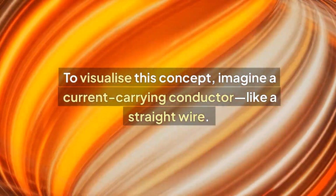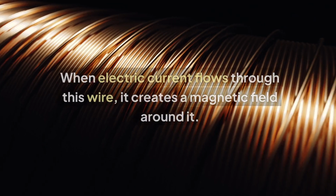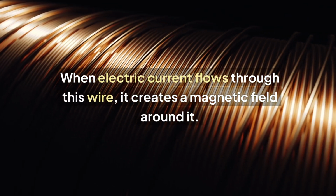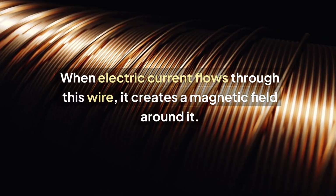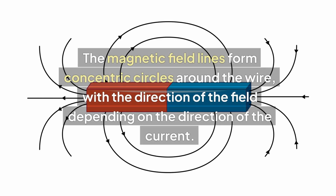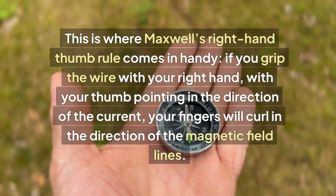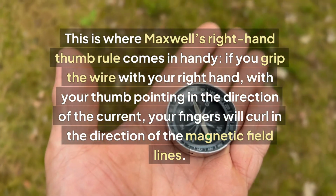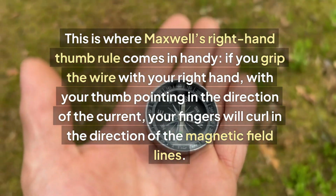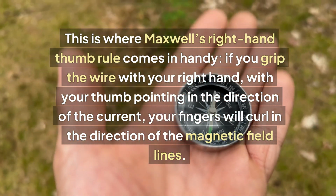To visualize this concept, imagine a current-carrying conductor, like a straight wire. When electric current flows through this wire, it creates a magnetic field around it. The magnetic field lines form concentric circles around the wire, with the direction of the field depending on the direction of the current. This is where Maxwell's right-hand thumb rule comes in handy. If you grip the wire with your right hand, with your thumb pointing in the direction of the current, your fingers will curl in the direction of the magnetic field lines.